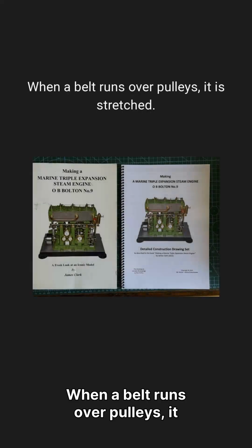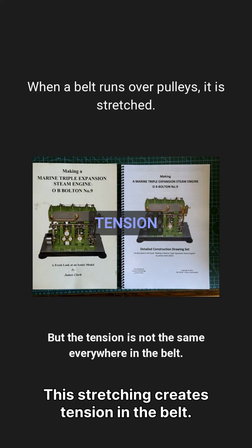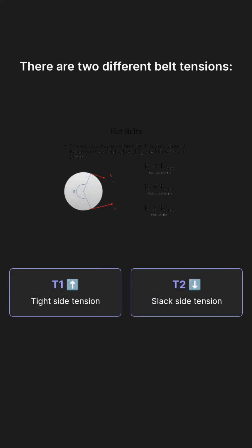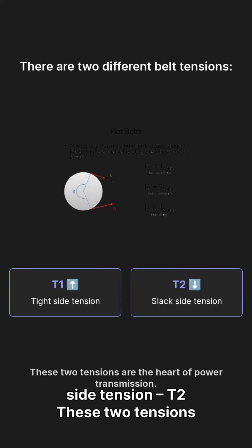When a belt runs over pulleys, it is stretched. This stretching creates tension in the belt. But important point: tension is not the same everywhere in the belt. There are two different belt tensions: tight side tension, T1, and slack side tension, T2. These two tensions are the heart of power transmission.